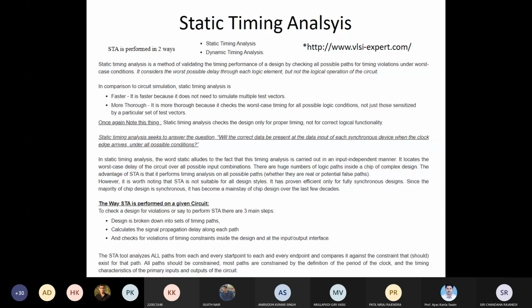Let's say a very standard academically used technology is 180 nanometer. That refers to your transistor length. Okay, so L size is fixed over your design, and W will vary according to your design requirement and calculation. Depending upon this W by L ratio, a set of libraries are created which consist of standard cells.